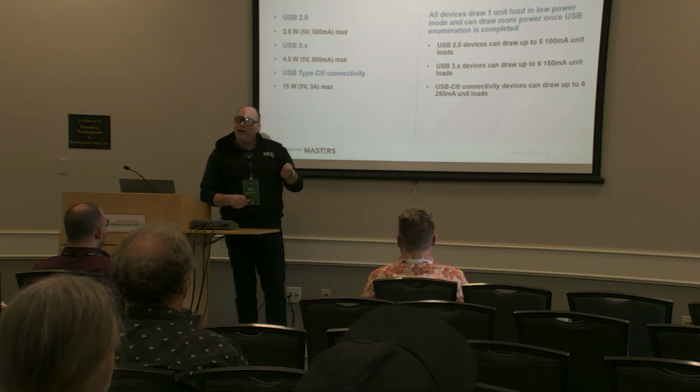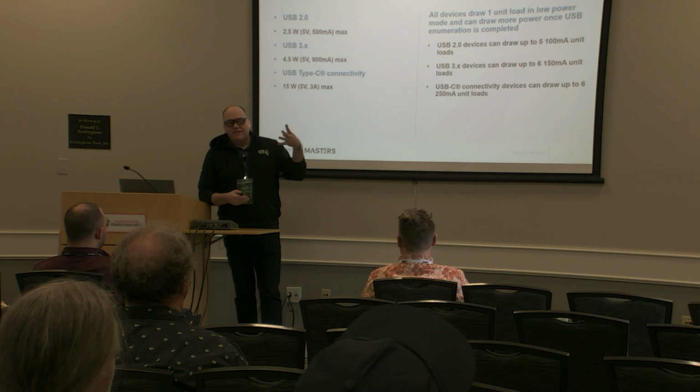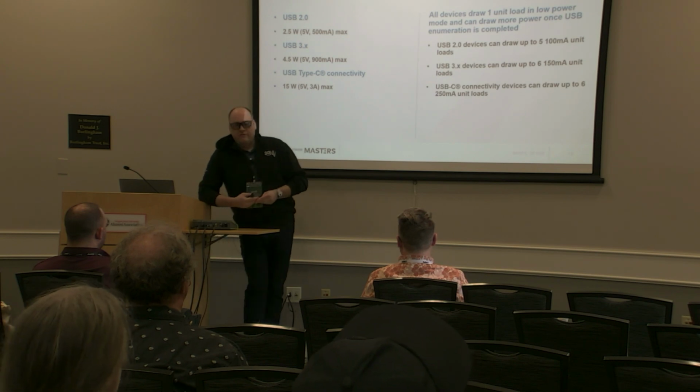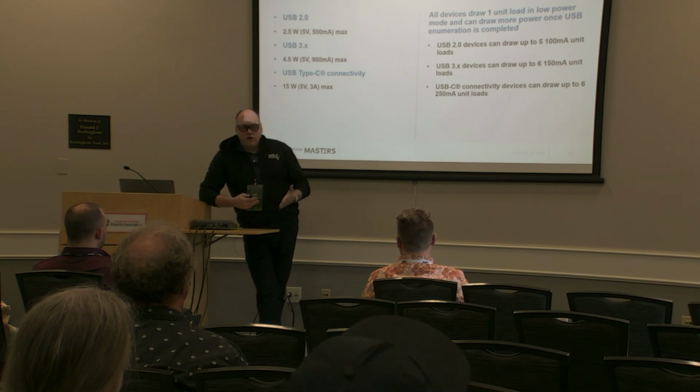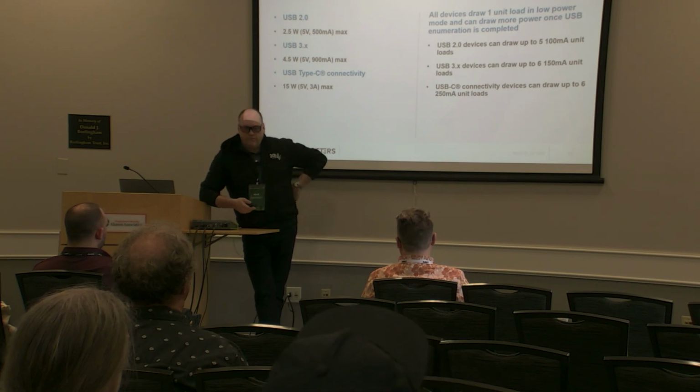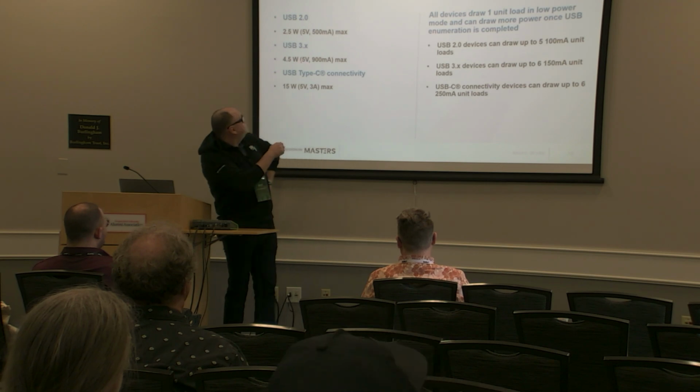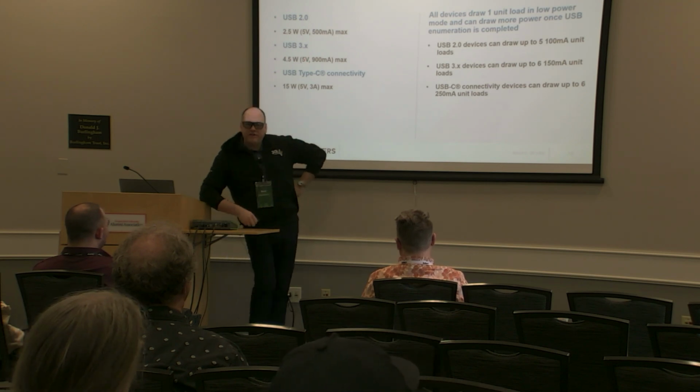So I plug in a third one that's 250 milliamps. Say we're on a 4-port hub here. I plug in a third one. It needs 250. How much does it get? 300, right? How much power have we used on a USB 3 port? All of it.